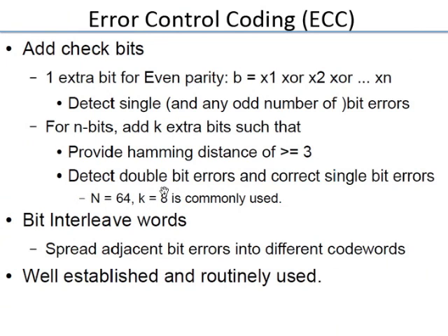For example, you can now have ECC DRAM, right? Basically, when you buy those, you have extra DRAM chips which have storage for these extra parity bits. And you can do this correction, single bit correction. But even within the chips now, SRAMs, large SRAMs, people have started to put ECC in them to deal with this problem.